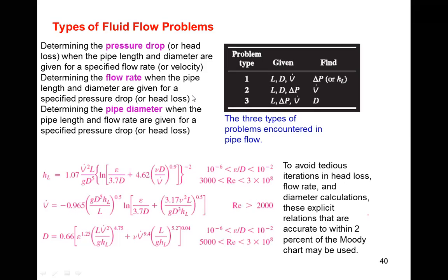You are supposed to calculate your pressure drop. So if everything is given, you can first calculate the friction factor, since your pipe material is given and velocity and flow rate are provided. So you can calculate how much the head loss is. Based on that, you can define what your pump should be. If that much is the head loss in 1 kilometer of pipeline, and you want to make the pipeline, let's say, 10 kilometers or 100 kilometers, that loss needs to be compensated. So to compensate the loss, you put in a pump.